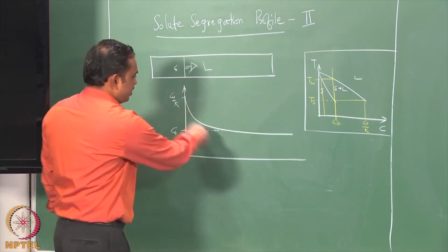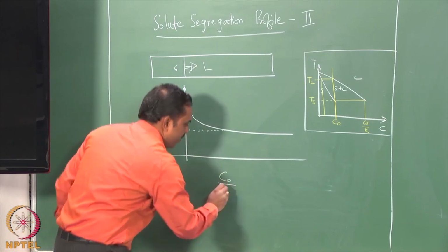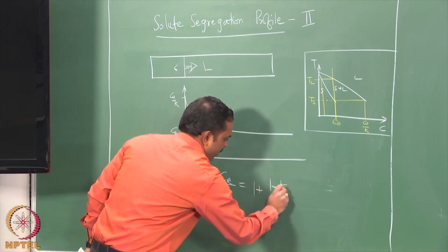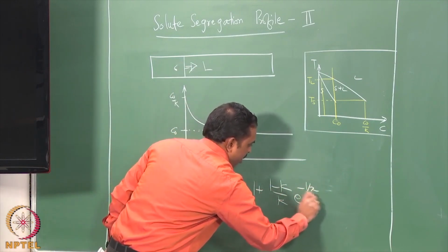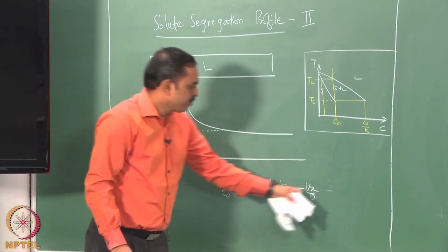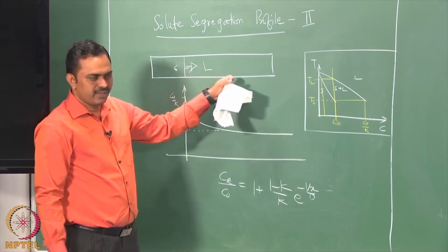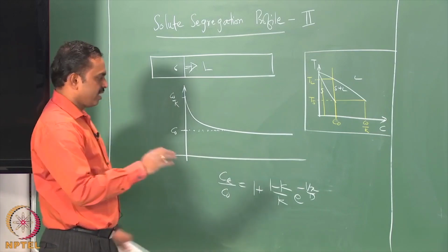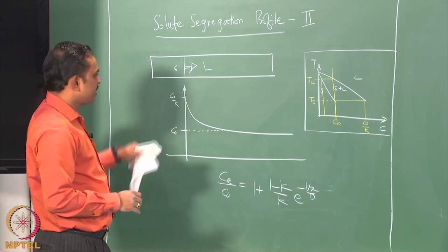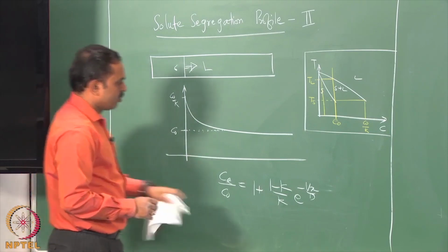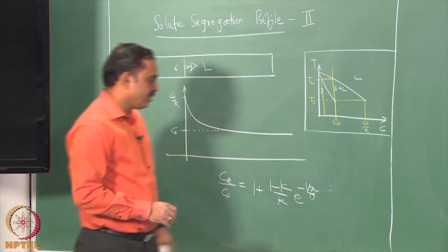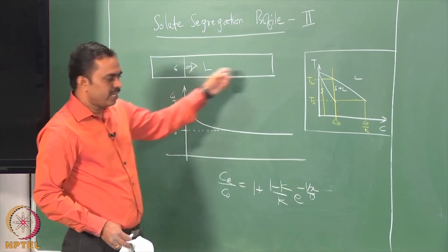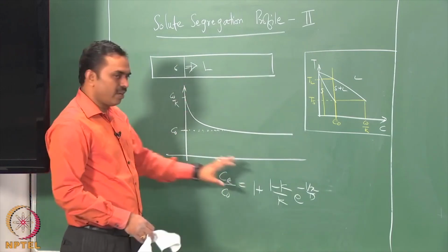And this profile is already given to you in the previous part. We have discussed it as the liquid composition given by this expression, exponentially decaying, and V is the velocity of the solid liquid interface. In the fusion zone, it is related to the torch velocity by a trigonometric function depending on the distance from the surface of the weld to the bottom of the weld. So, what do we know about V? D is the diffusivity of the solute in the liquid, and x is the distance from the interface into the liquid. That means this profile is available only for the liquid region.